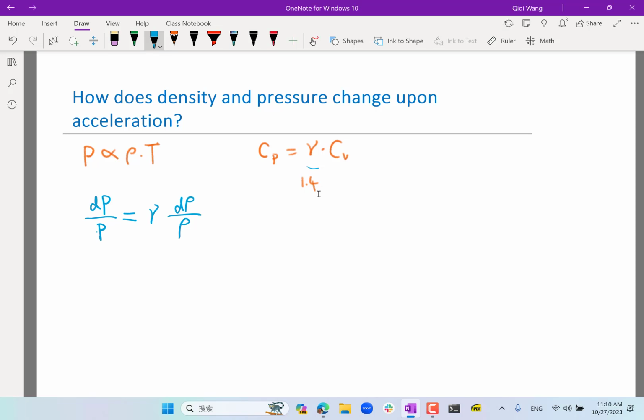And then what's more interesting is that we combined this equation with an equation that's basically Newton's second law, right? We combine this equation with u times du. So u times du in a steady state flow is actually the acceleration, right? It is actually du over dt, where the d means a Lagrangian derivative, the derivative of time when you are tracing along a fluid particle.